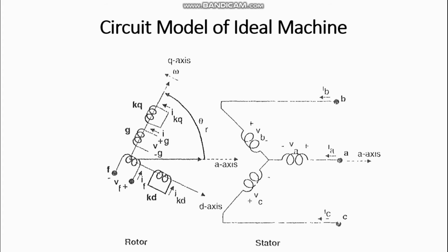What is the damper winding? A damper winding is like the squirrel cage induction motor rotor conductor structure; the same structure is placed on our synchronous machine. In the case of a salient pole machine, we place it near the pole face. So, pole base actually, not face, pole base. And these damper windings, like the squirrel cage induction motor rotor circuit winding, are also short circuited.